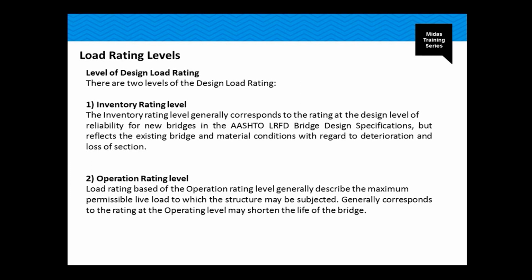This is why the inspection is so necessary to perform the bridge load rating. And then we have the operating rating level, which generally describes the maximum permissible live load to which the structure may be subjected. Generally corresponding to the rating at the operating level, it may shorten the life of a bridge.